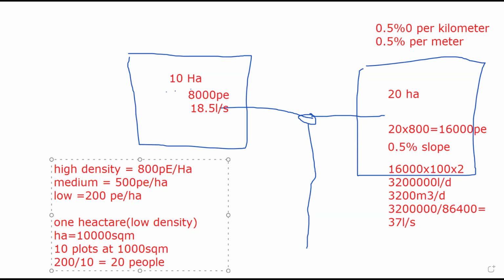You haven't finished explaining the 0.5% per. What of HDPE pipe? How do we also size that one? PVC pipe. Last week you said that PVC pipe is very smooth. So there are 3 nomograms. Like I also said in the WhatsApp group, you can see many charts online. But the one I have from my university is calibrated for PVC pipe, ductile iron, which is 0.4, and concrete pipe because it's rougher. Those things are the friction factor, or Manning's n, or Hazen-Williams ratio, whatever. We'll still come to that.